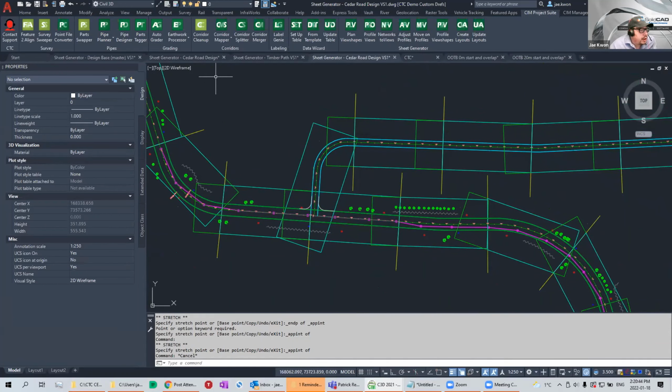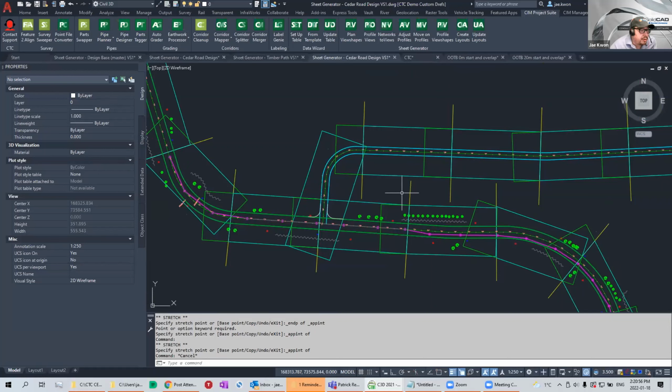whether you use multiple sets of layers, or whether you use this approach, you only need one set of layers if you separate it into separate drawings for each road. So that's probably easier to do for an entire subdivision where you might have several roads involved. Maybe the one drawing approach if it's a small project where you just have a couple of roads join up, then you can do a quick job with that.